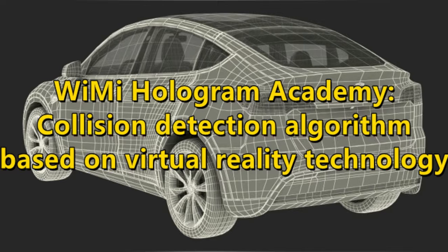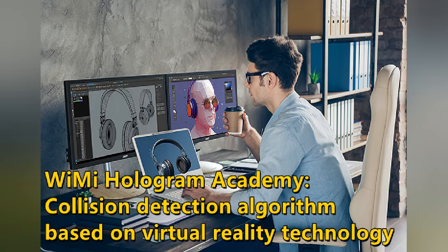Deformable objects can deform in motion, and the enclosure box method needs to rebuild or update the enclosure tree, reconstructing the entire data structure. The key problem of uniform space segmentation is to determine the proper cell size. The appropriate selection of cell size allows the algorithm to maintain a certain accuracy without too much cost. Compared with the surround box method, the spatial segmentation method has some advantages in computational efficiency, but when the models in the scene are dense and evenly distributed, the cells need to be further divided. The cross-test and storage between cells need large space, and the computational efficiency decreases sharply. It is greatly limited by being sensitive to the storage volume.